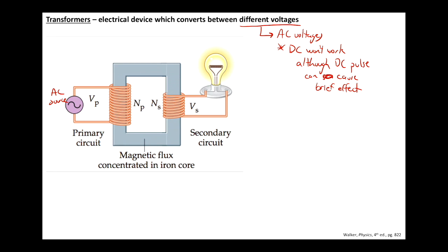Nearby, and typically really close nearby, if not sort of nested inside of each other, we have another circuit, a secondary circuit. There is no electrical connection between the two, so don't make the mistake of thinking that the rectangle of iron there is something that can conduct. Instead, it's fully insulated from that, and no current can pass through it. Instead, we're going to use it to help direct the magnetic flux in just a second.